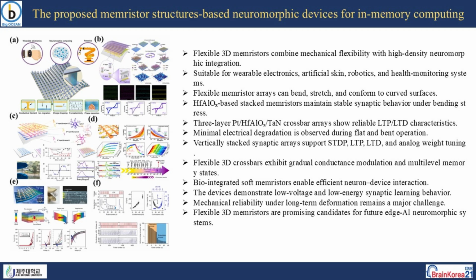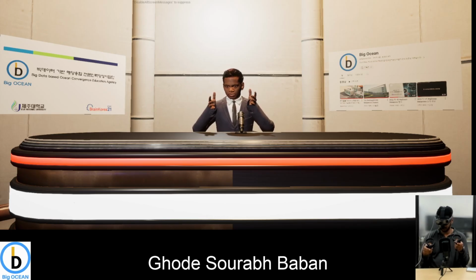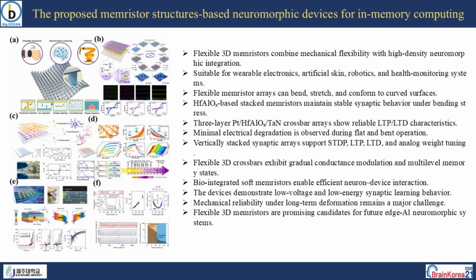bending state. So in the figure you can see the three-layer Pt/HfAlO2 crossbar array shows LTP and LTD characteristics, with minimal electrical degradation observed during flat and bend operations. Also the vertically stacked synaptic array can support STDP, LTP and LTD, and analog weight tuning.